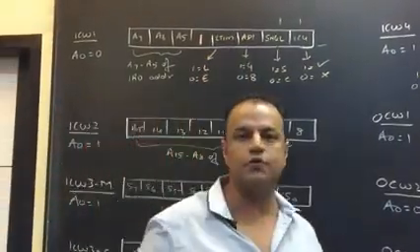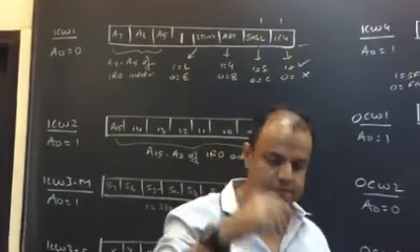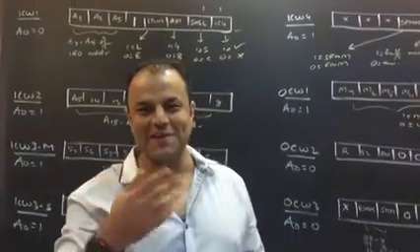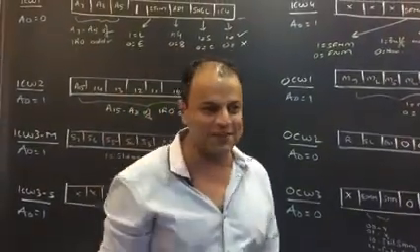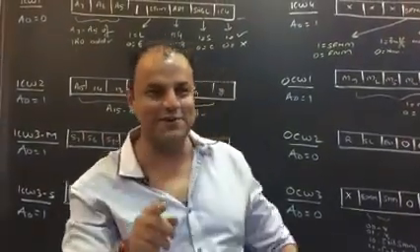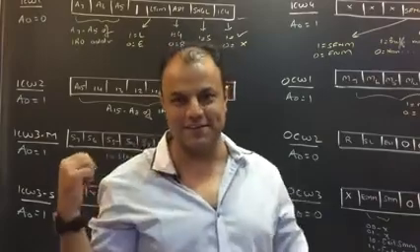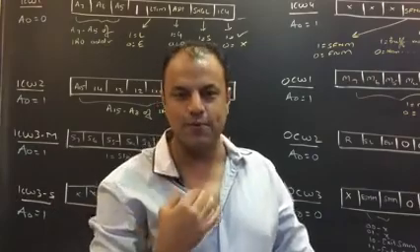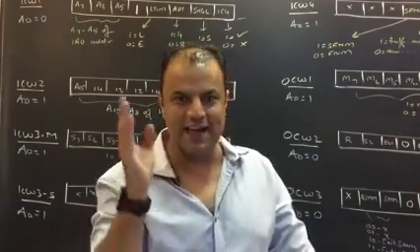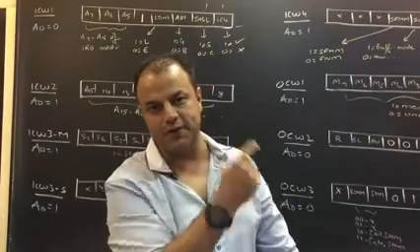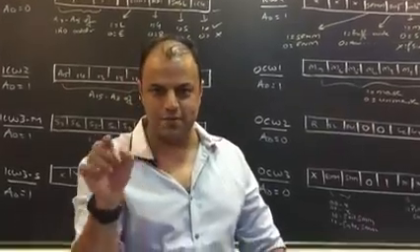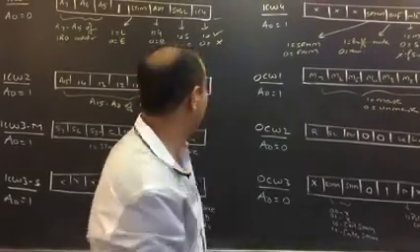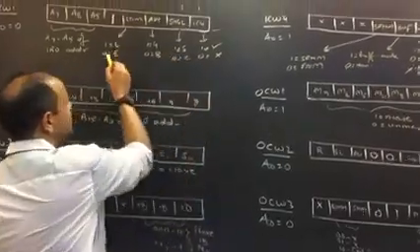LTIM. LTIM stands for Level Triggered Interrupt Mode. Say it again. Level Triggered Interrupt Mode. If you have seen the video of 8259 architecture, the video just 2 videos before this, I have given the introduction where I've said the programmer chooses whether we want interrupts to be edge triggered or level triggered. So this is where you make the choice. 1 means interrupts are level triggered, 0 means interrupts are edge triggered.